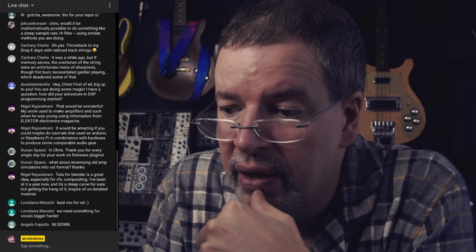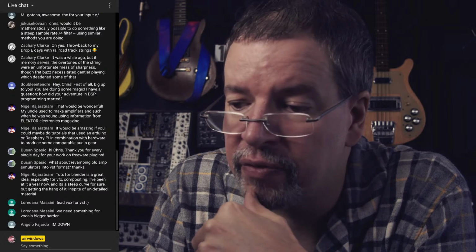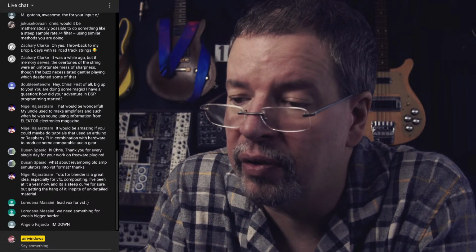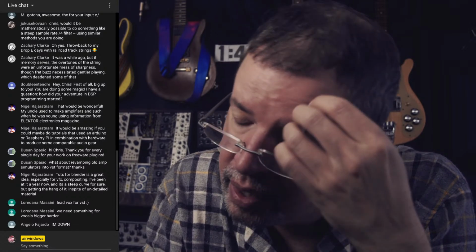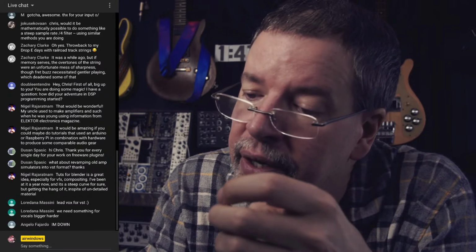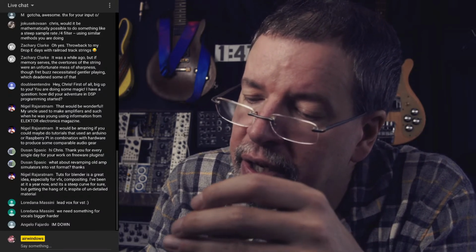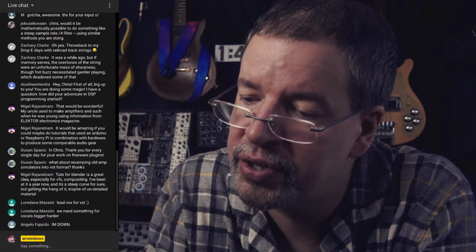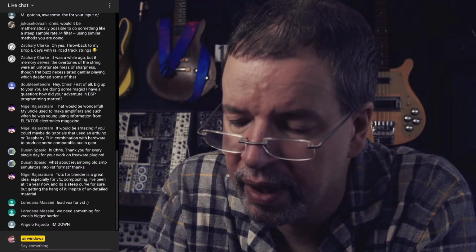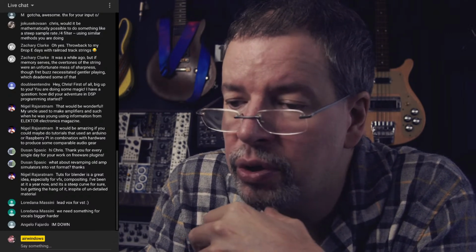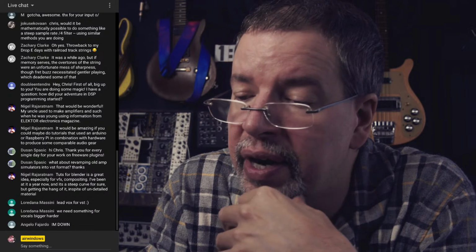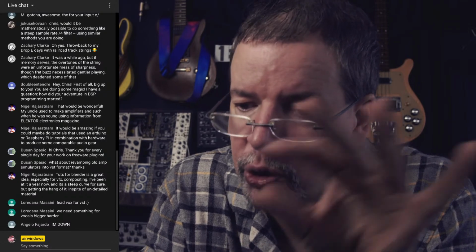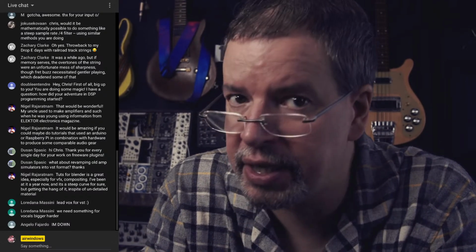And the 4007, if I'm remembering the number correctly, is the up to 18 stage shift register where you can only get access to so many of the output points. Internally it had, I think, two 4 stage and two 5 stage shift registers inside it. So what you would do, and it was implemented in such a way that you could have a shift register number of something like 12, 14, 15, 16, 17, and 18 possible steps.